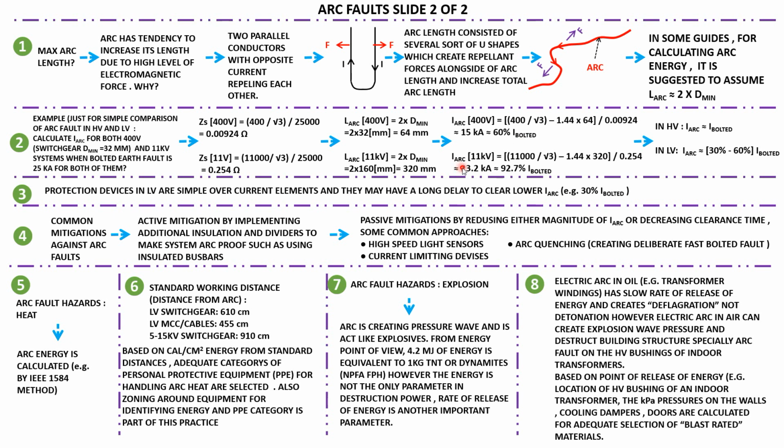Whereas in 11 kV, the original 25 kA short circuit level is reduced by the arc to 23 kA, almost only a 7% reduction of the short circuit level.